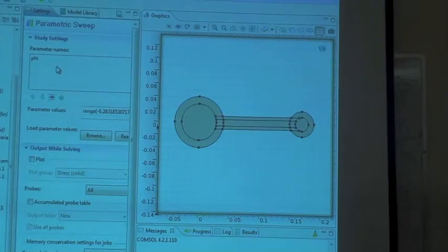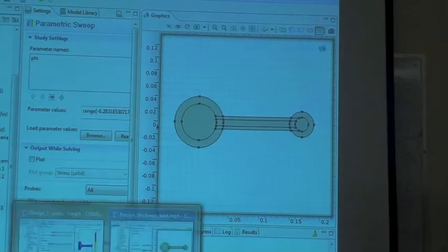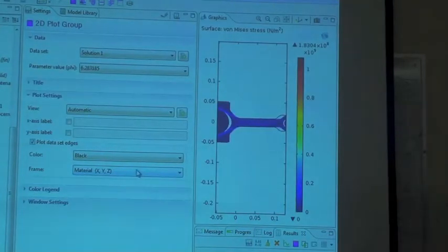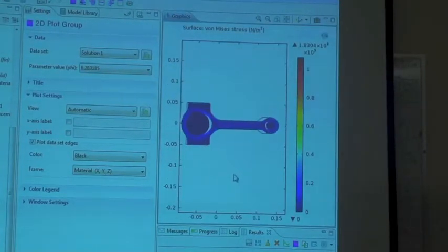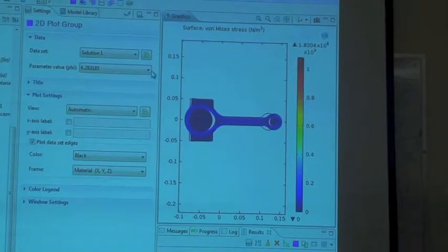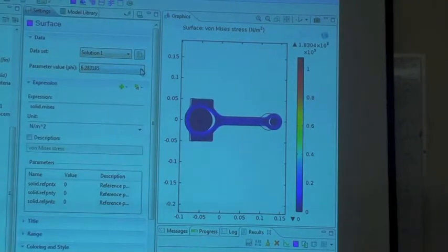It's only changing one parameter at a time, but you can do multiple iterations: fix the phi, sweep through thickness, then sweep through length. That would be a lot of data. Actually, I think there is a feature in COMSOL where you can set an objective function, and it will keep going until it optimizes. That would be a nice feature for the design course when we modify it, to introduce optimization.